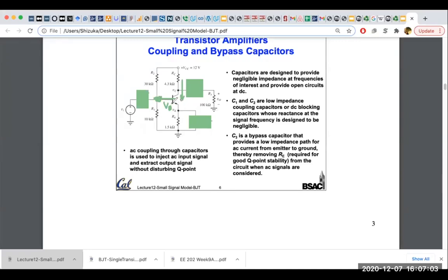And this current is found with two equations. You have to do an analysis here, because there is a VB voltage minus VBE. Now we are here at this point: VB minus VBE minus I emitter times R4 equals 0.